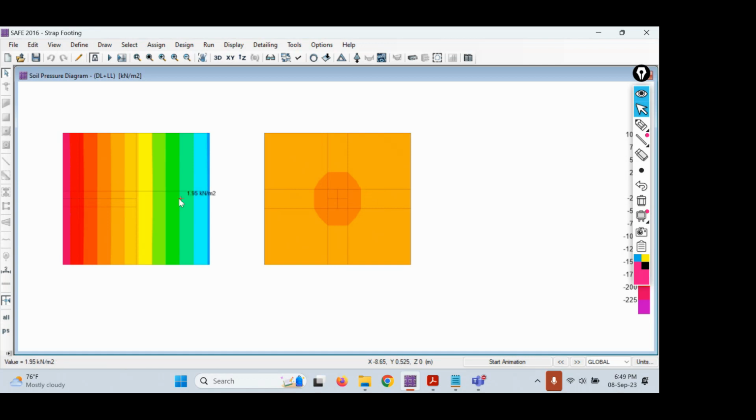So you can see in the first footing, uplift is going to happen. Why do I say it is uplifting? Because the negative value is changing to a positive value. If you consider this as the first footing and this as the second one, at the right edge of the first footing the value has changed to 53 from a negative value. The value is minus 198 at the column, and when you move, it is 53. That means in the first footing, uplift is going to happen.